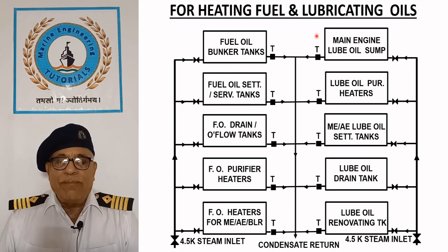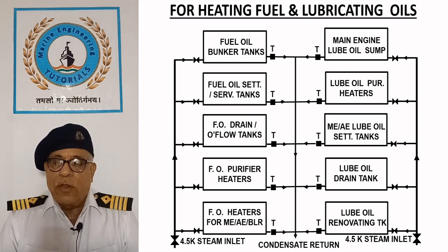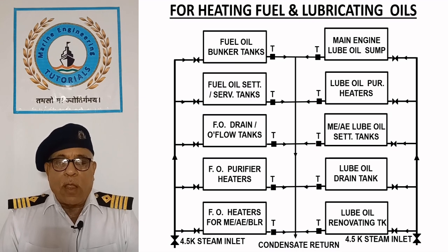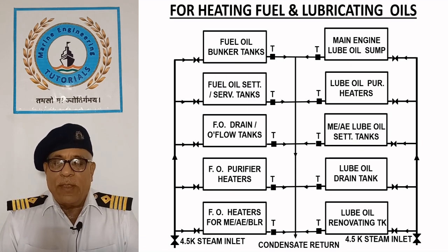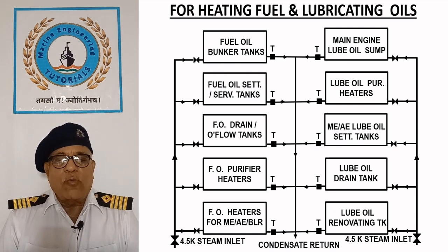A steam trap is fitted at the outlet of each heater to fully utilize the latent heat of steam. It allows only the condensate to pass and prevents steam from escaping until it has fully condensed, ensuring efficient heat transfer. The condensate returns to the hot well.